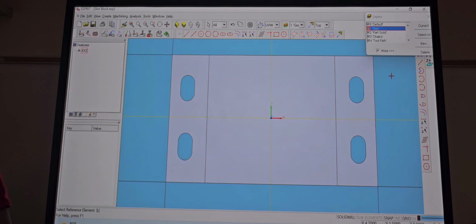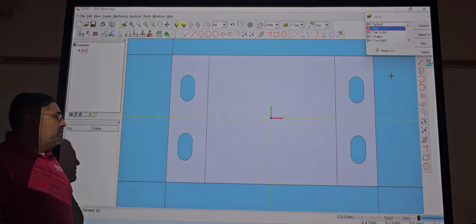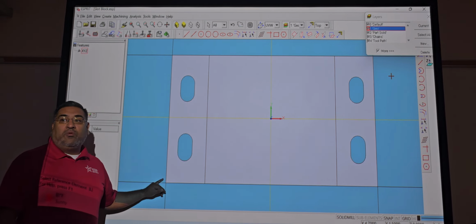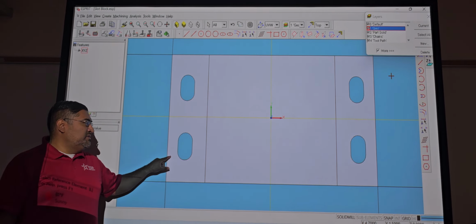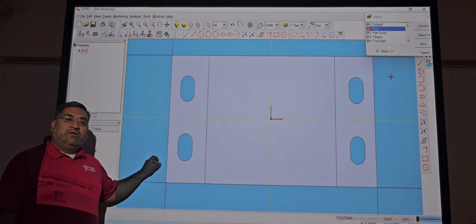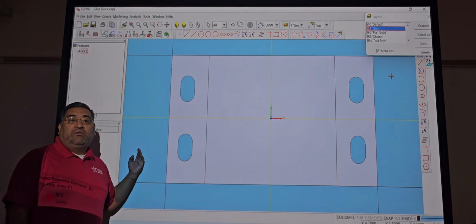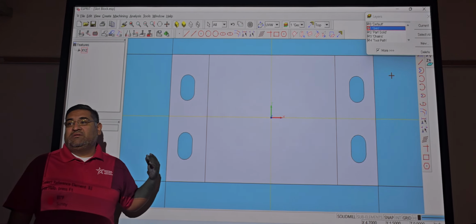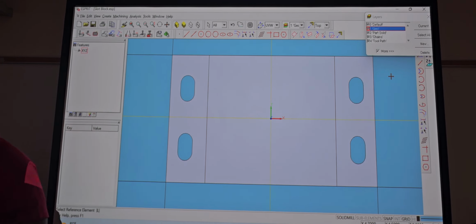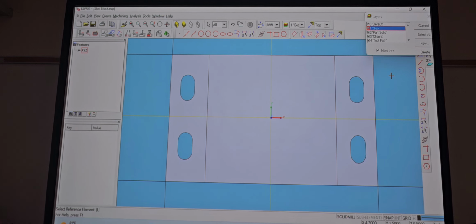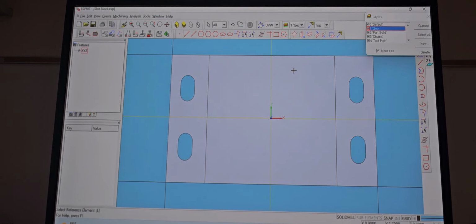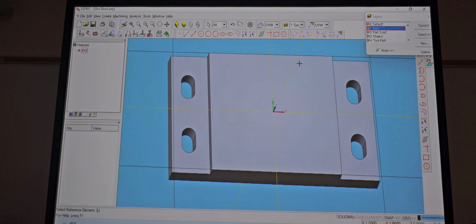So ideally, on all sides, you'd have them out 250 thousandths more. Yeah, because I know that later on, that could create a problem over here, because if the tool isn't thick enough to come over here on the side, it's gonna leave a little bit of material on there, right? So I'm gonna make sure it goes over it, and it cleans it up. Does that make sense? And you're gonna face all sides anyways. Yeah, you would want to profile it too. So I'm gonna profile this one.